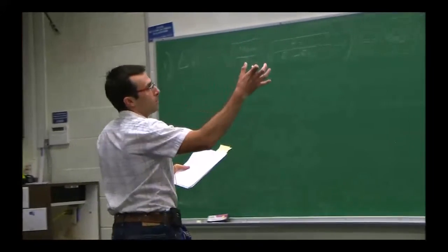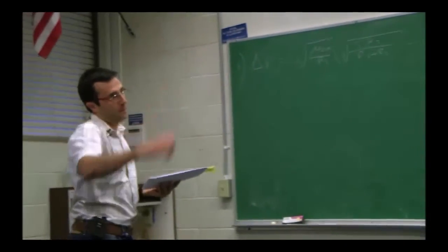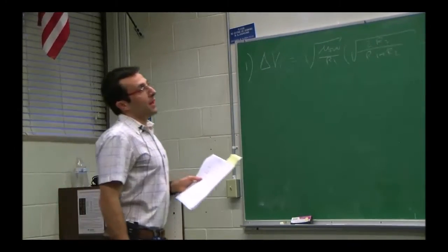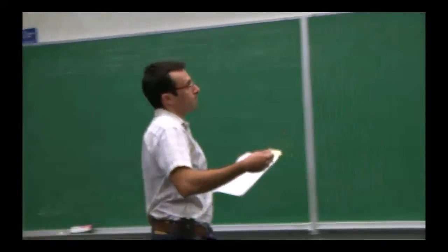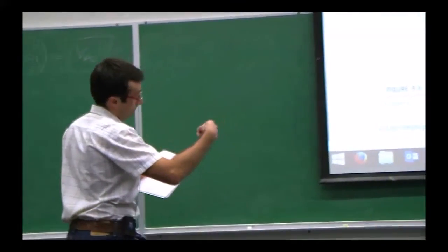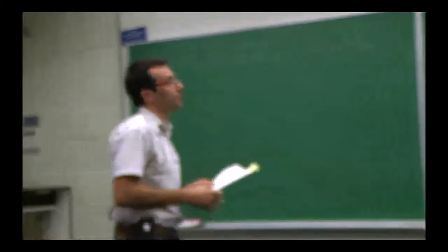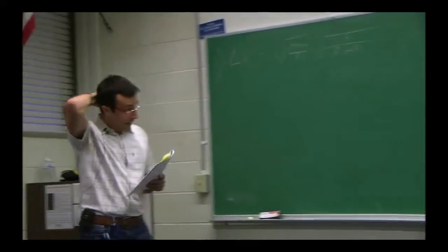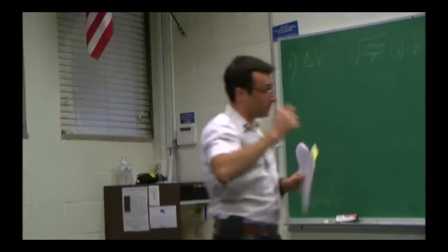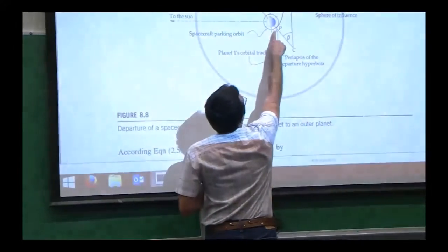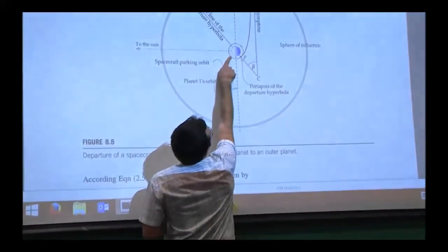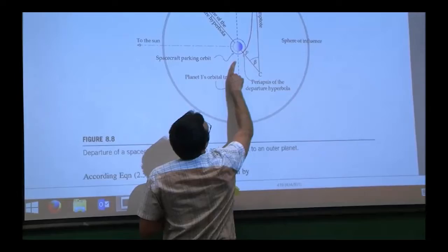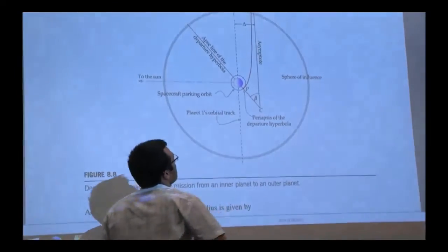So you're flying on, and that's what we're going to assume. Let's say that you're flying on a circular orbit of some radius r, okay? And when the time is right, you transfer to the hyperbolic path that will go to infinity. So what is the next step? Well, the next step is characterizing that hyperbolic path, because I need to make sure that this angle, beta, is correct. So I need to make sure that I fire the engine right here, not here or somewhere else, because my V infinity has to be parallel to V1. So I need to make sure about beta.